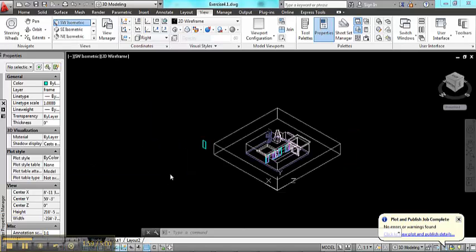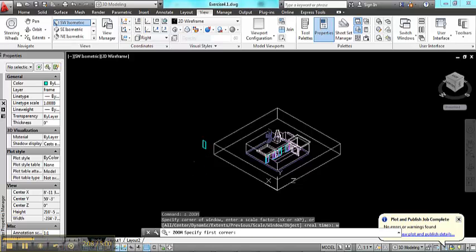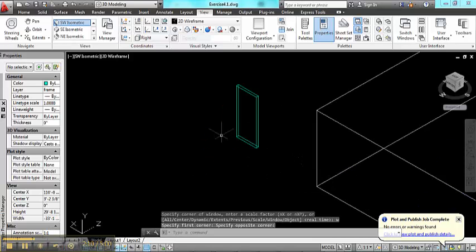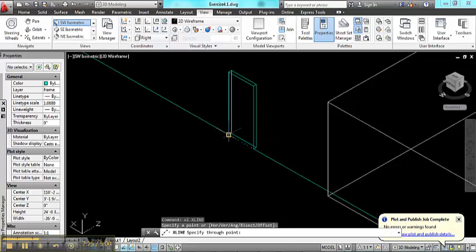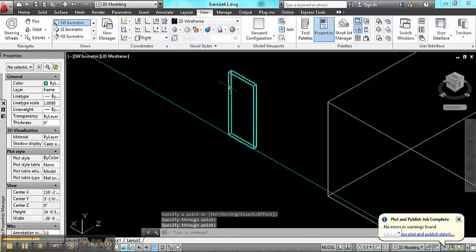So looking at my frame from Southwest view, this is what I see. I'll zoom in closer, zoom, window. Now I'm going to draw the frame within the box. So what I'll end up doing is sort of eliminating portions of the frame, and then I'll place glass in them. So I'll use the X-line command to generate some construction lines so that I can then draw the frame on the surface of the box.